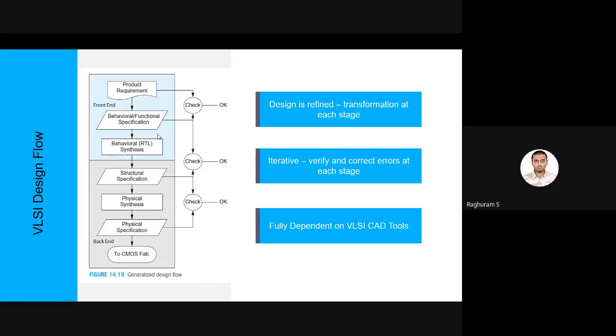For example, you might have 10 cases, and for each of those cases you want to do some particular action, and it's not easy for you to do that directly at the gate level. For example, if you sit down and try to code in Verilog, you have to do a lot of work. If you want to directly code at the gate level, you have to have the gate level, what logic you are going to use, what type of gates, AND gate, OR gate, NOR gate, what is the whole decoder circuit should be ready with you before you can actually write the code.